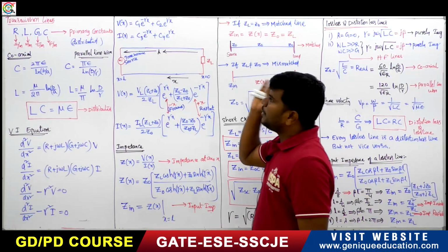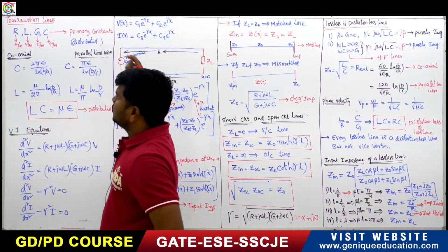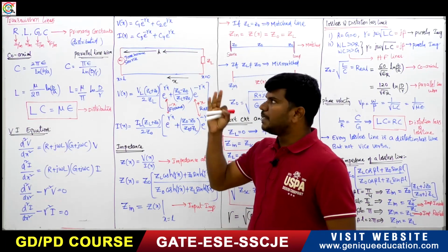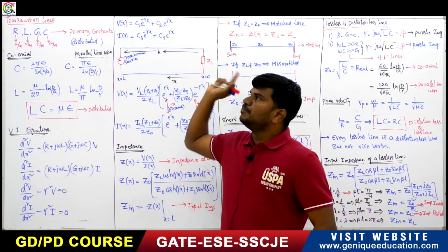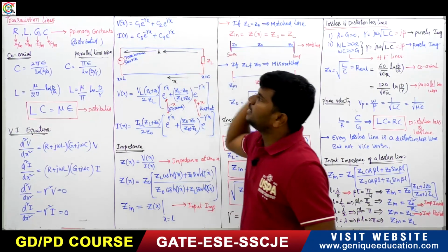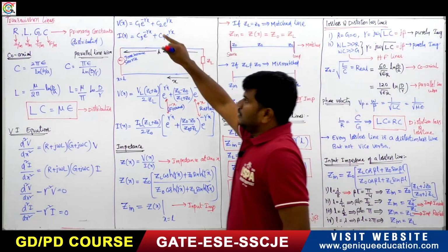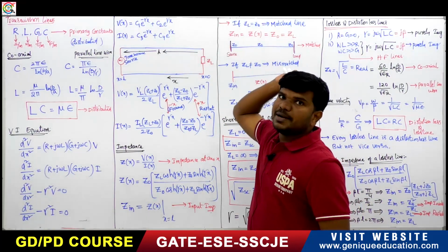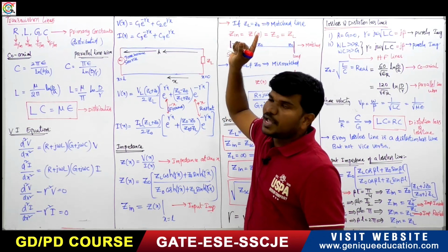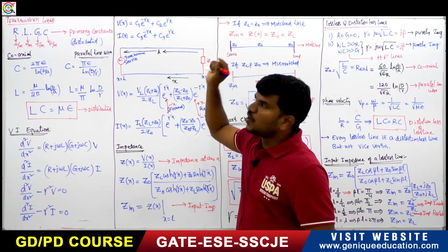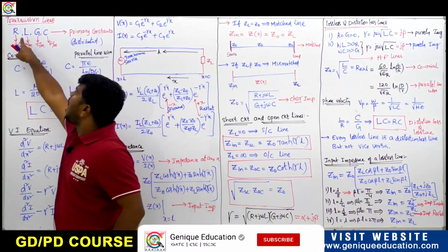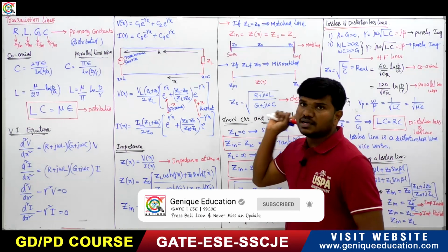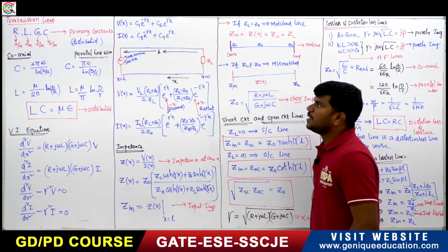Here very important parameters you should consider. If you take the EM waves, there are mainly three medium parameters: sigma, epsilon, mu. Sigma, epsilon, mu are the three important parameters, called the material constants. Here, there are four parameters, which we call RLGCs. RLGCs are called the primary constants.